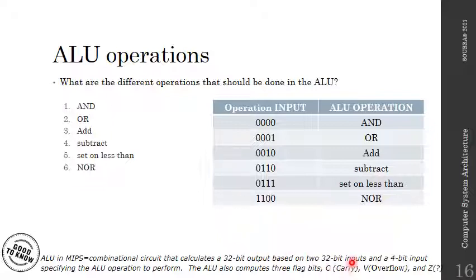Fair enough? So this means that the result that you're outputting, we're going to find out if it's the exact result or a result with a carry that you can use. And the overflow, apparently you've seen it as well. This means that whatever you're doing, if you're using 32 bits and the result cannot be represented in 32 bits, you're representing the result only partially, and there's an overflow. So the output will not fit in the 32 bits.